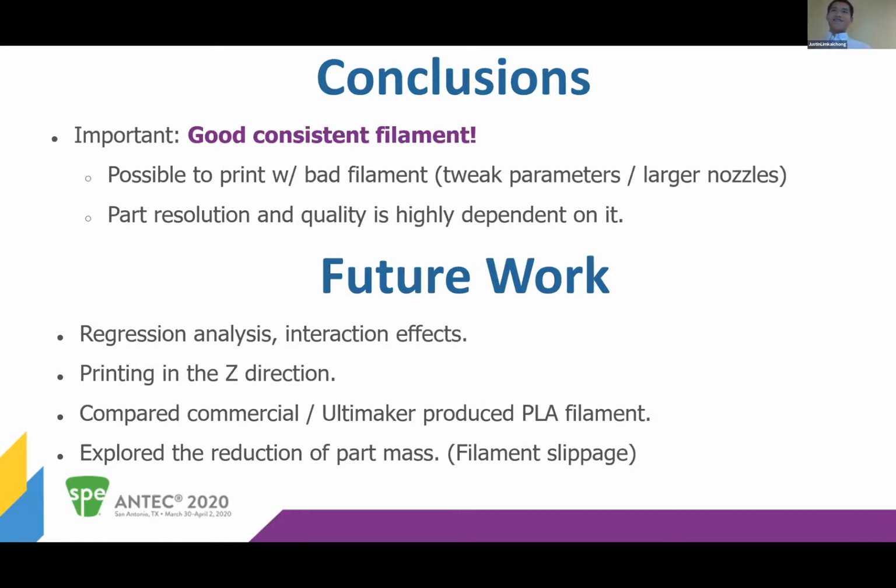So in conclusion, I can't stress enough that good and consistent filament is something we really do need. However, don't worry if you have bad filament, it's not the end of the world. You can still tweak your parameters and maybe play around with larger nozzles to kind of normalize that bad filament, because this is highly dependent on your filament quality. This will basically affect your quality and your part strength.